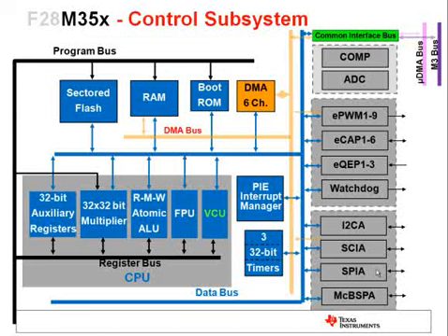Engineers usually start development in floating point, then translate the code into fixed point before implementing them in their final designs. Eliminating the need for this conversion reduces development time as well as prevents most scaling and saturation issues. Through benchmarks against other C28X processors, floating point instructions help reduce the cycle count for math functions by 52%. Double precision operations will require support libraries.